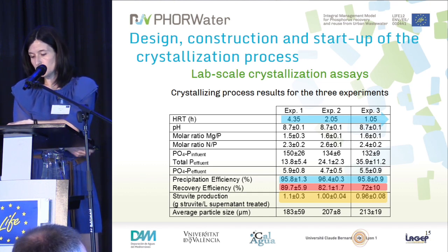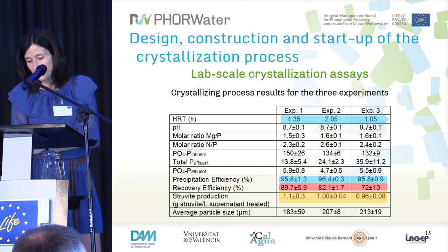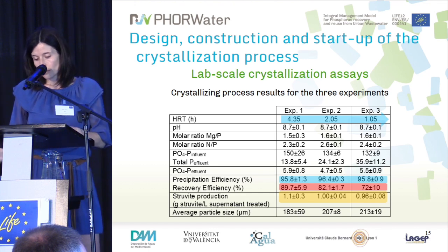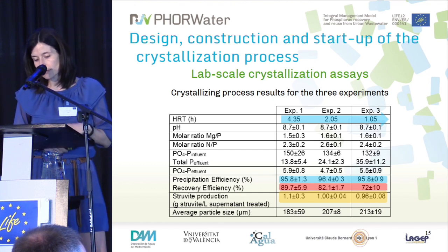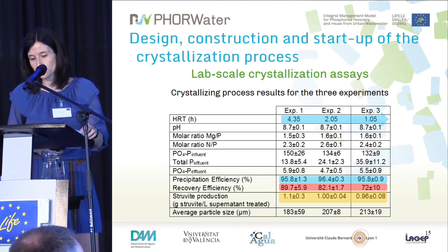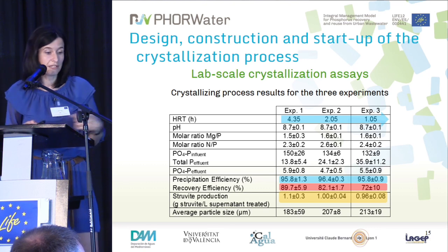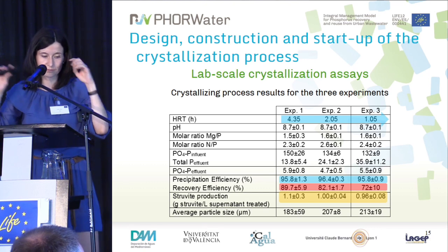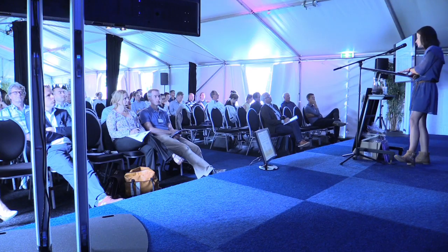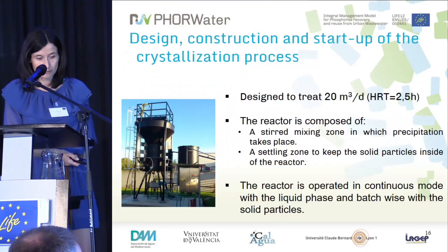But what we can see in this chart is that as we decrease the hydraulic retention time, we also reduce the recovery efficiency. And that's actually something logical because of the dynamics. The settling is going to be worse if we increase the flow. So that was expected.